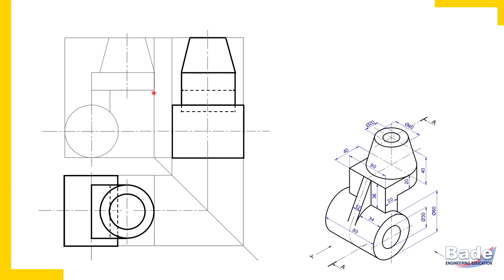The dotted line is for this corner or for this corner. A corner is formed by three edges. Watch here, this corner. Against this corner there is an edge. Remember, a corner is formed by three edges. This edge is parallel to height. This edge is parallel to length. And from this corner there is a third edge which is parallel to the width axis. In the side view, width is horizontal. So even if you have erased that dark continuous line, there should be a dotted line here, that is the hidden edge from this corner. From this corner, this is that hidden edge.